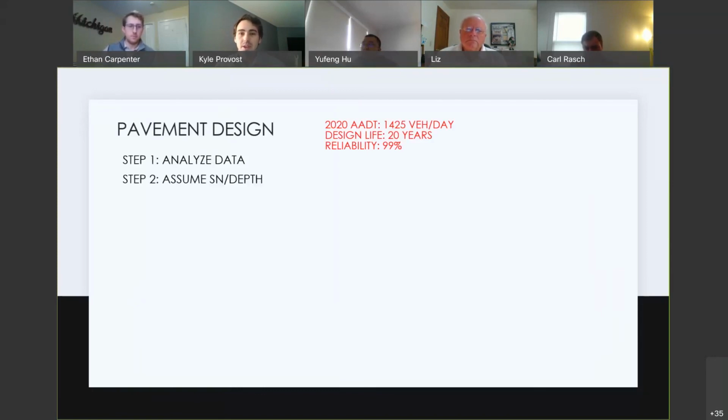In the pavement design, the structural number for flexible design and concrete slab depth for rigid design must be assumed. Through trial and error, the actual values will be determined. Assuming a structural number of 3 for flexible and 7 inches for rigid, we can now calculate the estimated single axle load acting upon the pavements. Using the ESAL equation, we find the corresponding HMA ESAL to be 843,500 and the concrete ESAL is 180,700.